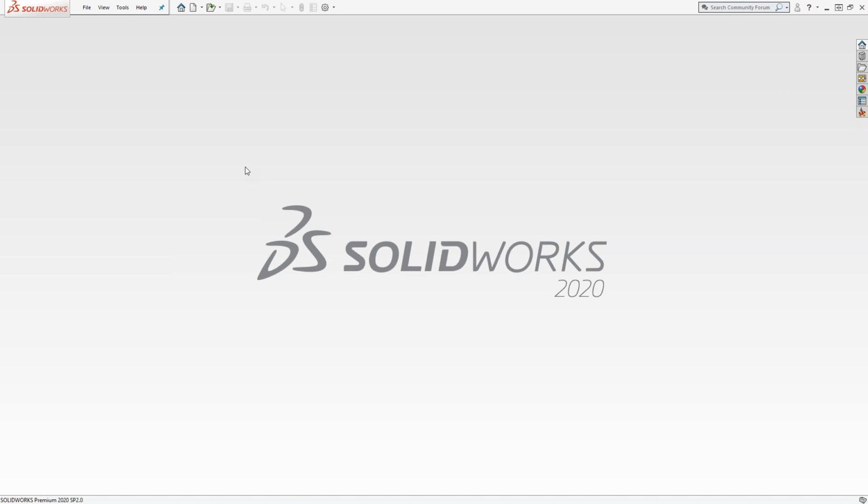What we could probably do, if that is an application that's applicable to other people, is I can either find that file or I can just recreate it. We can do it in a future SolidCAM Live class if you find that you guys are doing a lot of broaching. Every toolpath inside SolidCAM has the ability to do the transform command. So if you're doing splines on the outside of a turned part, use the toolbox cycle and then use the transform fourth axis command to do all the splines. You can go around the part as many times with as many angular increments as you need. It'd be easier to show it than to talk about it, but I can't find the file.